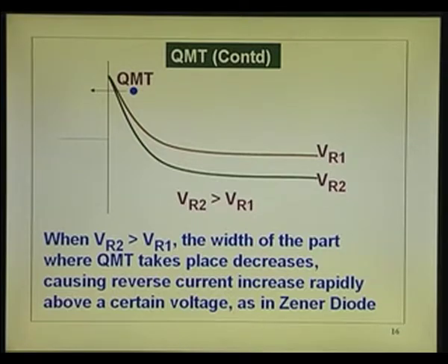Forward, there is a factor n coming up, which is slightly more than 1. It will not be 1, 2, 3 and all that. It will be just 1.05, 1.06 of that order because of these effects. Okay? But it can kill if you do not take care of those peak electric fields. If there is field crowding somewhere, okay, in the junction region, if there is any field crowding, that E peak will go up, the crowding effect.